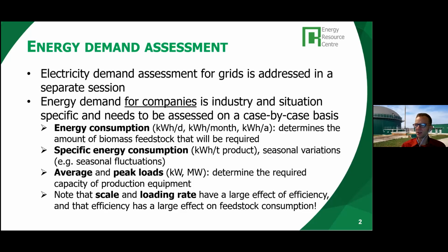What is important there is the specific energy consumption related to the production output of the company or the industry, and we can express that as the kilowatt hours per ton of product. And in many industries, you'll also find quite substantial seasonal variations, related to the availability of primary materials for processing.